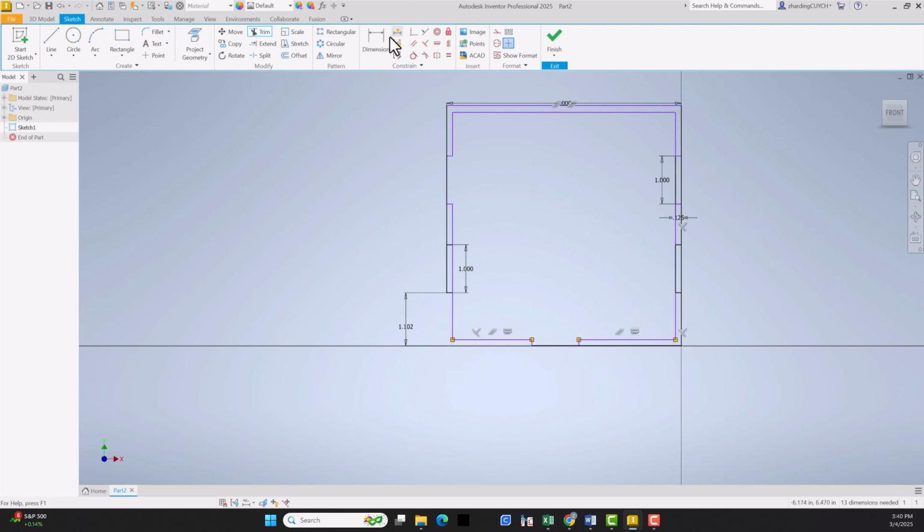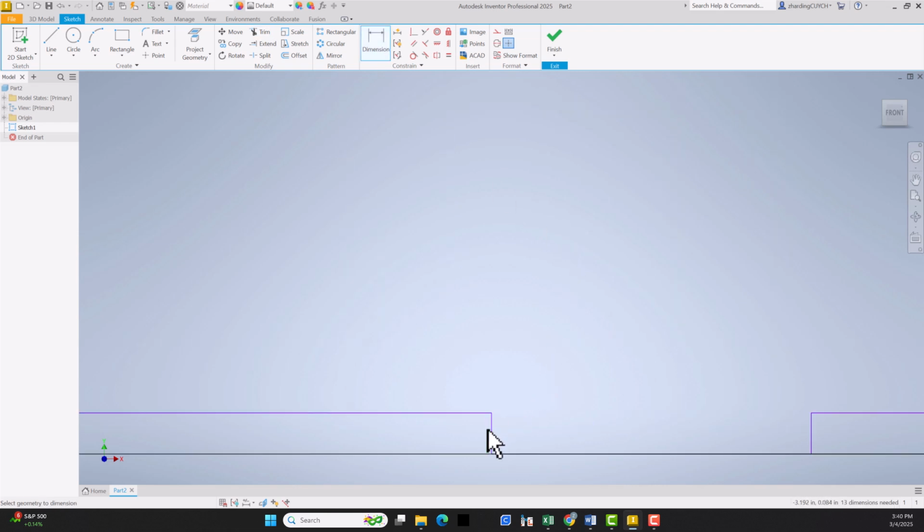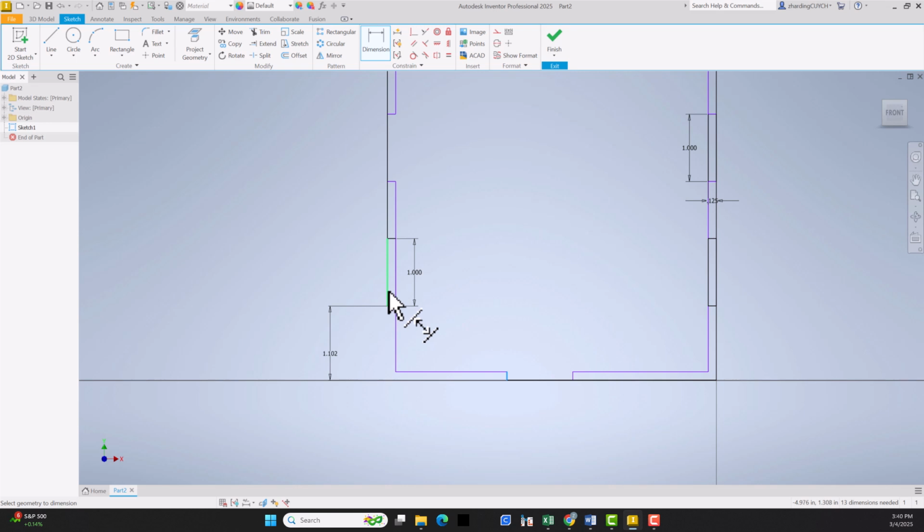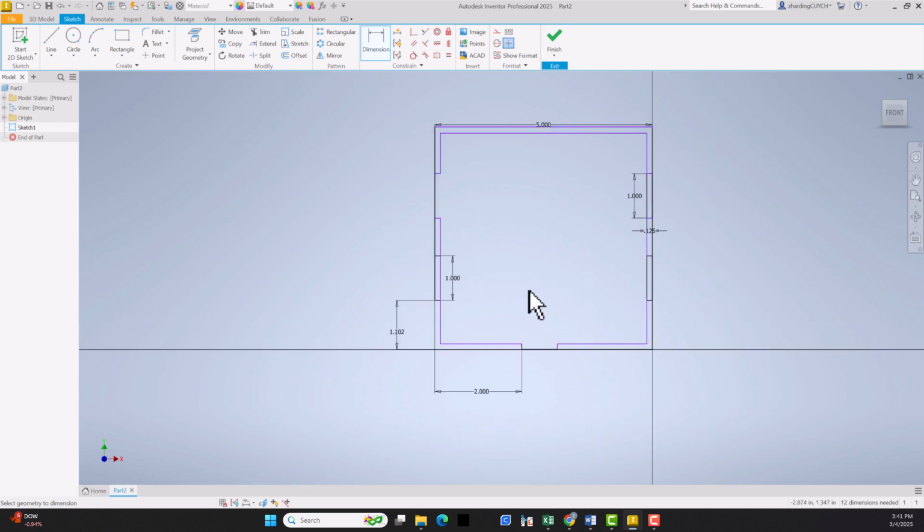Alright, and then you can go through and adjust your positions if you need to. I want this to go from here to here. Right, and I want that to be, some people get confused on how to center their items. If this is 5 inches and I have a 1-inch tab that leaves me 4, so it needs to be 2 on each side, right? So 2.0, enter, and I can push that little tab over to center. Alright, so just use common sense. If it starts jerking your panels around when you're trimming, cut your dimensions out. But you should be able to get to the point.